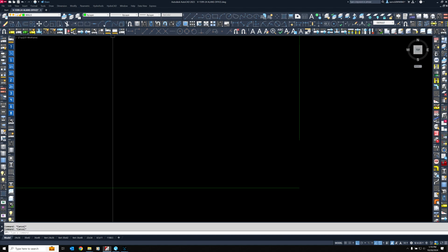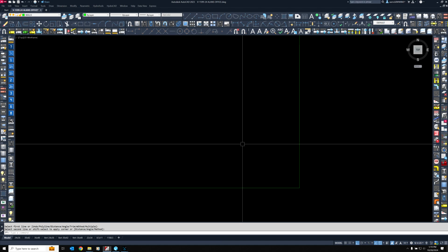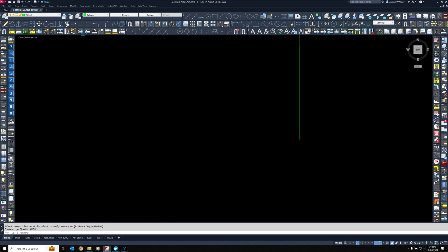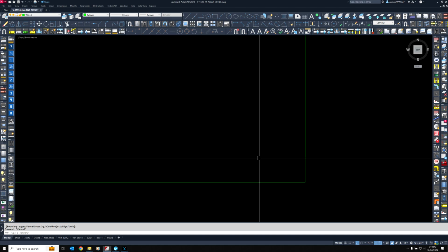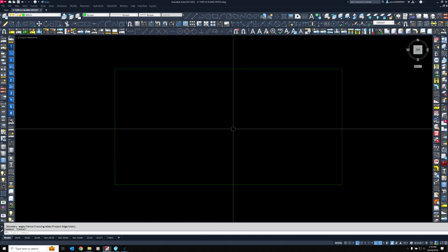There's also a tool right here called Chamfer, and there's a tool called Extend. We can drag these together. We can use Join. We can use Extend. We can use the Chamfer button. Chamfer, if I touch this one and this one, boom, they're done. If I undo that one more time, hit Extend, I pick the one that I want it to go to, and then I hit enter, and the object I want to actually stretch will bring them together. All right? There are so many ways to do the same thing in this program.